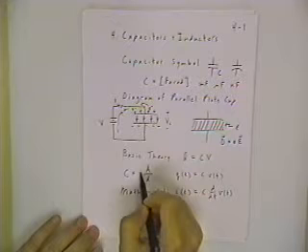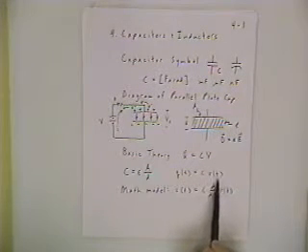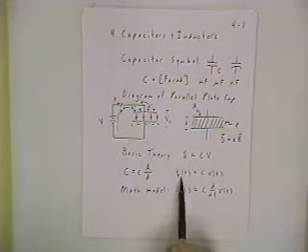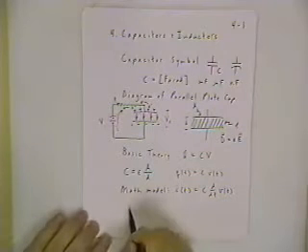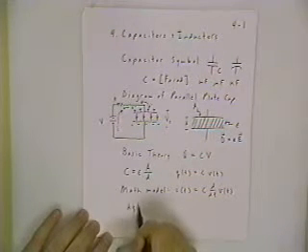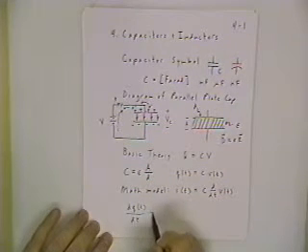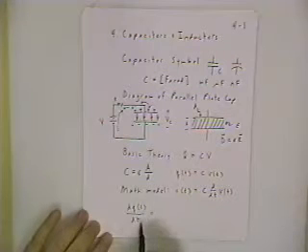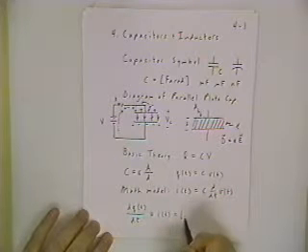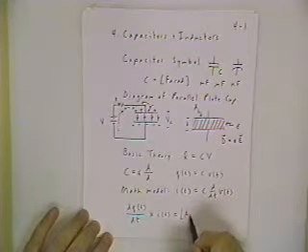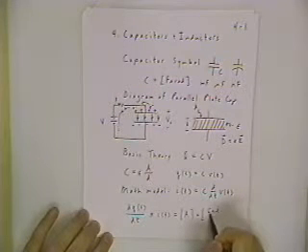Simple equation with the more complete expression that says Q as a function of time is also C times V as a function of time. And now the interesting thing you can do is differentiate this equation once with respect to time. If you recall, the time derivative of charge, dq/dt, would be measured in units of coulombs per second. Well, that's the basic definition of current, in SI units of amps or capital A, which is also units of coulomb per second.